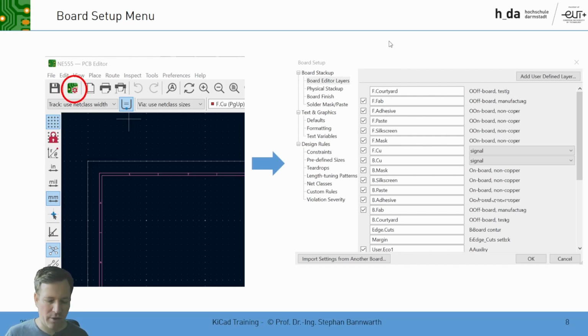The first thing which we are going to do is talk about the physical setup. So which copper layers do you take, which prepregs, and which cores. Then we talk about the board editor levels, so what kind of signals we route on which level of the board. Then we talk about the PCB constraints. These are the mechanical constraints from production mainly.